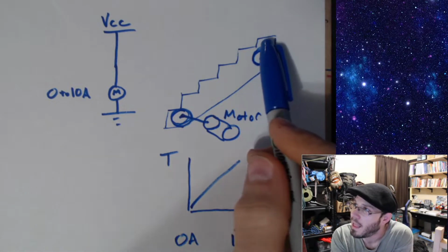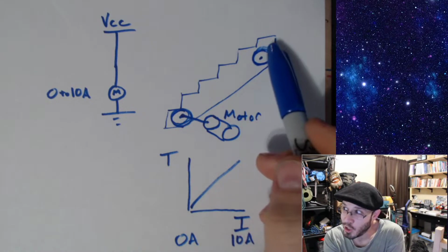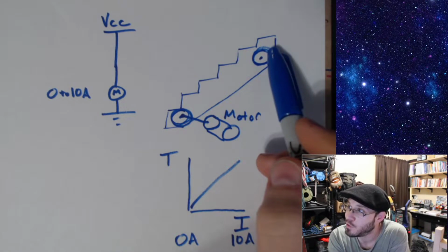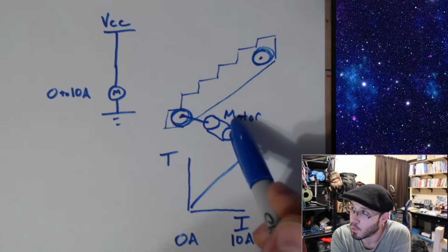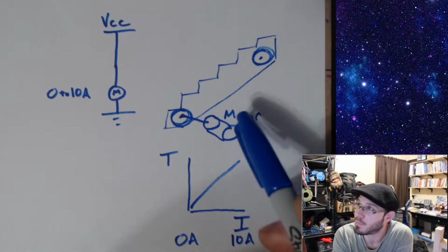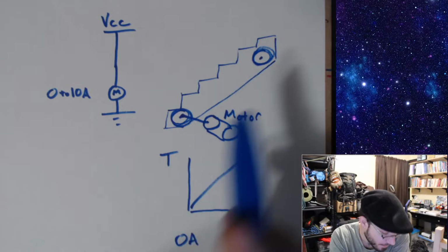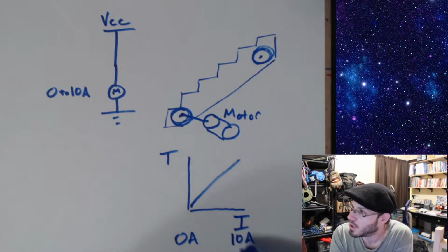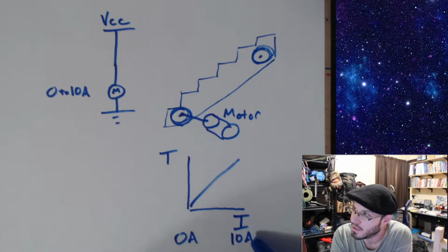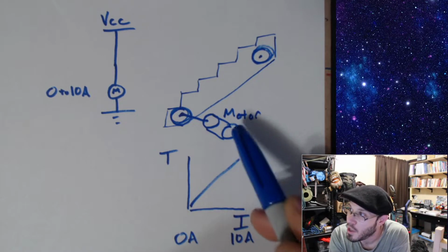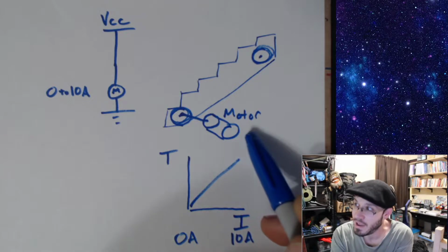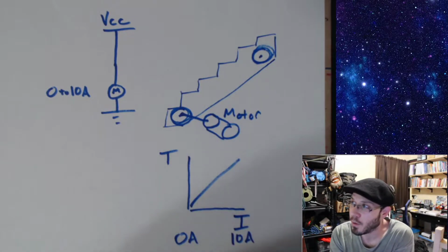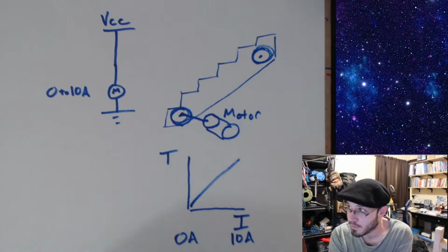Well, when that occurs, your motor has to exert quite a bit of force to suck in your flip-flops into the escalator. And if you monitor the current consumption of this motor, you can detect this failure and then shut the whole system down for safety reasons.